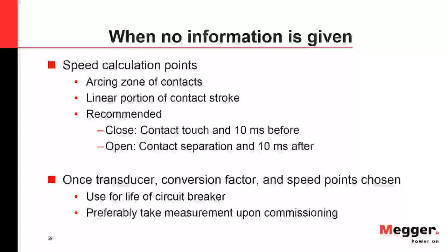So, a couple of things. Time and travel analysis is critical. Not only time, but travel gives you overtravel, it gives you stroke, it verifies the dashpot is working, and verifies that the velocity of those interrupters is correct.